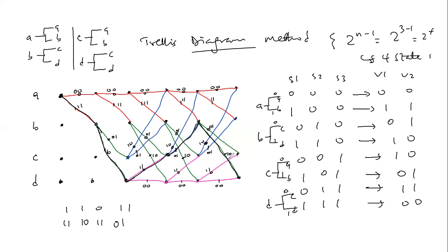Okay. So that is 1, 0. I see that this is consistent with what we transmitted earlier. Now, what if there is an error? Say, rather than receive this, let's assume this is correct. So let's assume we now receive 1, 1, 1, 0, 1, 1, 1, 0, 1, 0. So it means that this particular bit is in error.